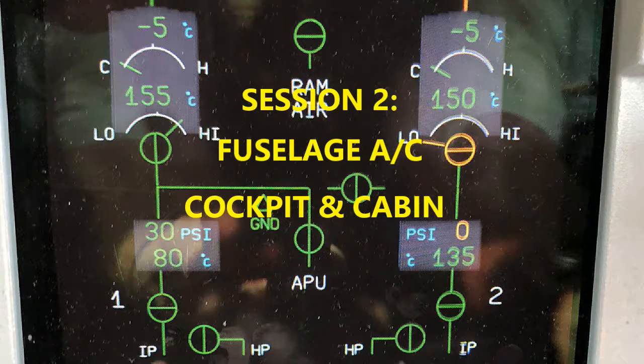Now I want to mention the ram air inlet actuators. I mentioned the flap actuators earlier, maybe in session 1. The air inlet flap actuators open and close the ram air inlets. They receive signals from the pack controllers as to whether to open or close. They're installed on the ram air inlets and the fuselage belly fairing. If you need to access these actuators, you will do so through the same panels, 191 and 192. That reinforces which panels to access for many of these different components.